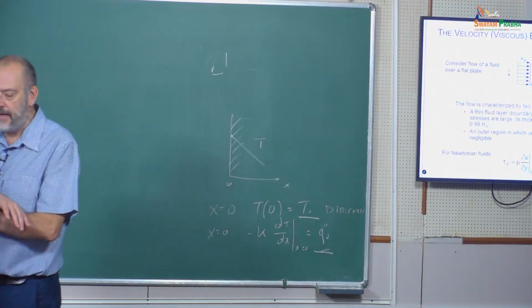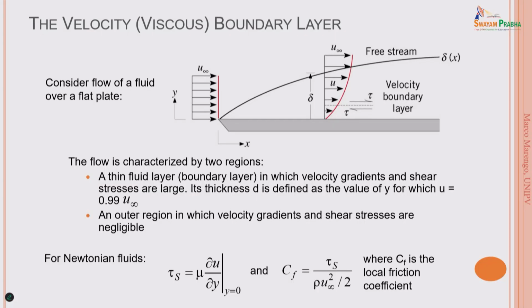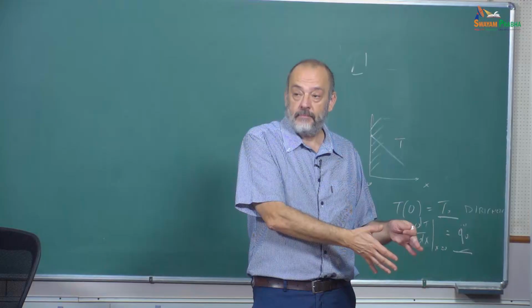At the end, we have a kind of curve on a surface that says how thick the boundary layer is. What is inside the boundary layer? Inside the boundary layer, we cannot neglect the viscous forces. This means that inside the boundary layer, we have a change of the velocity due to the fact that we are already feeling the presence of the wall.